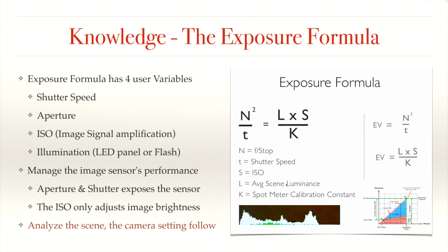And I mentioned this in the previous slide. If you look at the shadow areas and the bright areas or the midtone areas of your scene, the luminance is different coming off the reflected areas in that scene. And this affects the saturation level of the image sensor. In a shadow area, you will have a lower saturation level of the sensor, in those pixels in that area. And in a well-lit area, you will have a higher saturation level and SNR in those pixels. So you need to look at the pixels, not only the sensor.